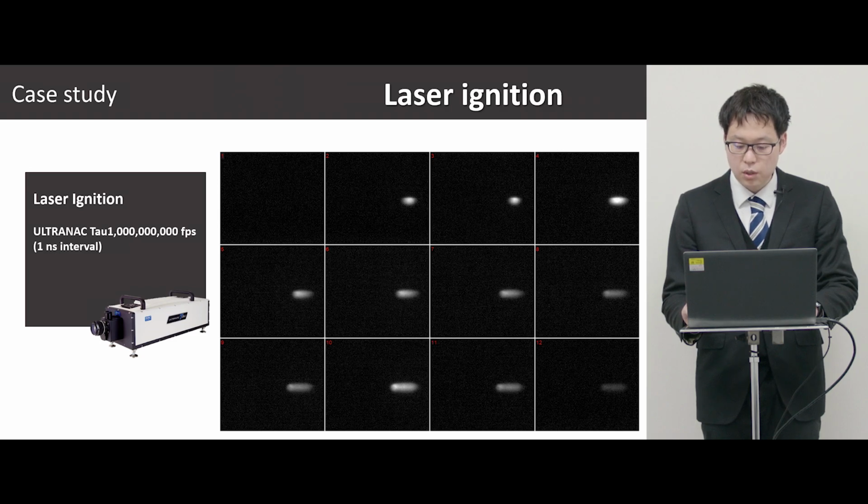Laser ignition utilizes thermal plasma formed by the laser breakdown, enabling ignition at any point by adjusting the lens focal position. This allows multi-point ignition at locations distant from the combustion wall, particularly advantageous for the large engines used in power generation.